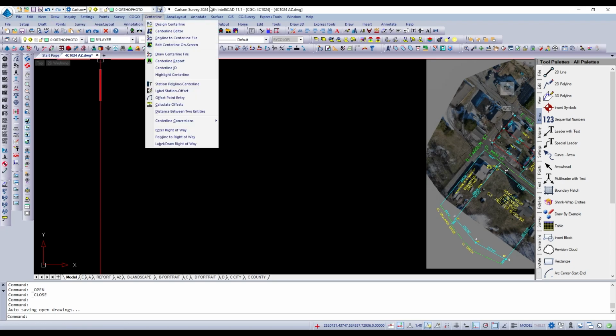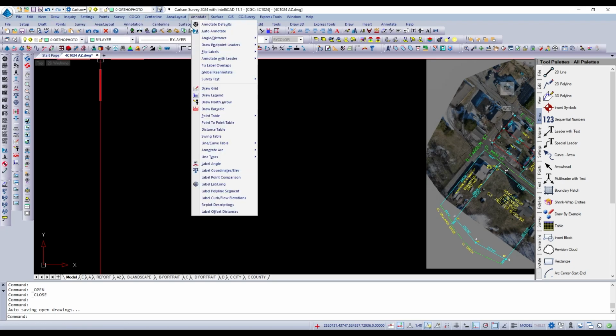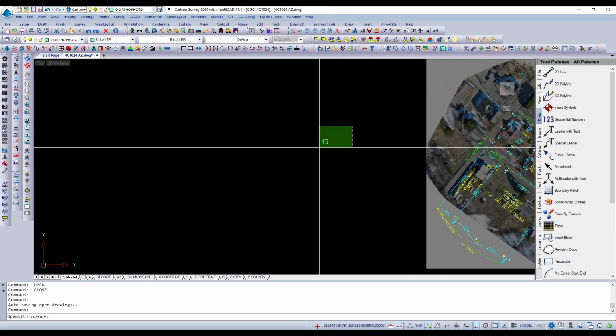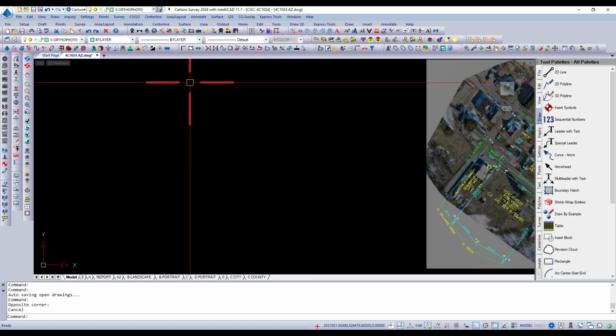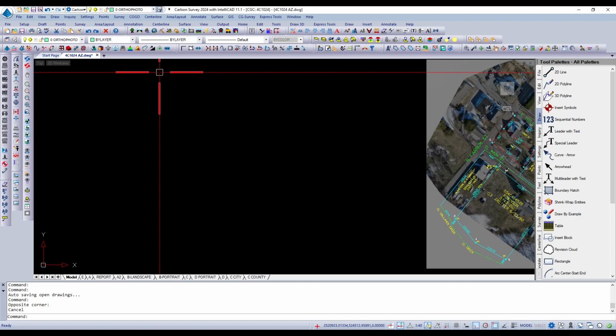So you are presented with some choices within the CAD program. You've got multiple ways of doing just about anything that you want to accomplish. So you ought to use whatever you feel is most efficient for you and whatever your most efficient use of time is. But to me, when you're doing simple things like drawing a line, it is much quicker to enter L on the keyboard than it is to go up and do a pull down menu and find the command and then execute it that way.